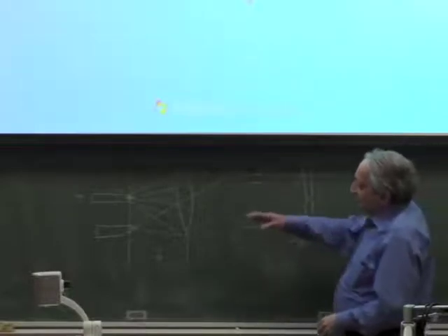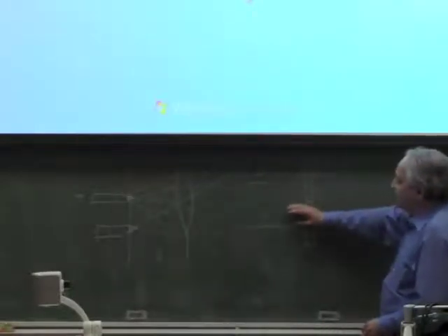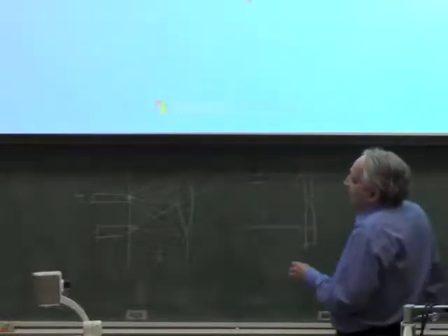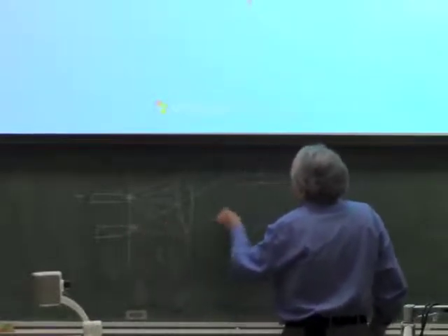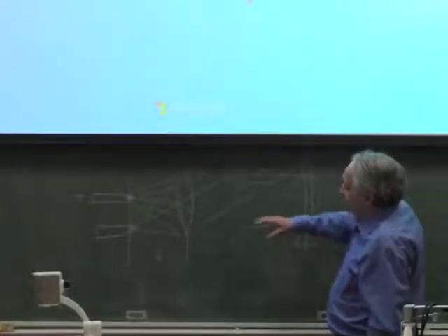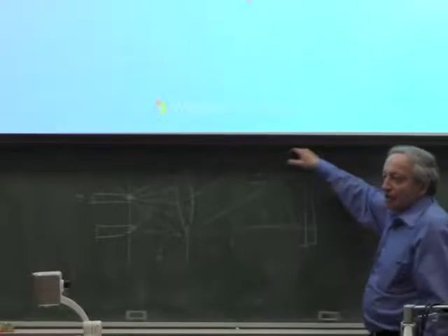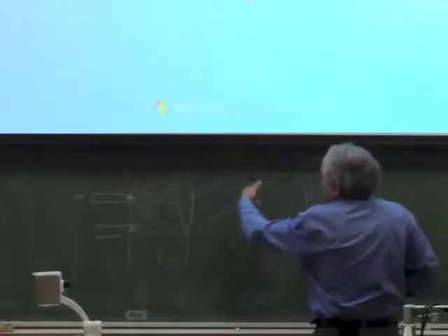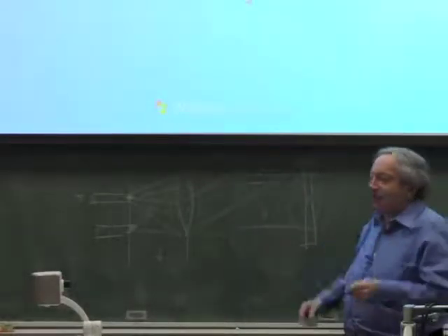Now it is true that if the LED is non-uniform, if I turn it, I'll get the light spot a bit brighter here, a bit brighter here. There'll be a small error in position. But if I move the LED to here, this whole beam will actually go this way, because the central ray going to the center of the lens is not changed. So if I move the LED, this whole beam will steer. And I showed it to you last week with the laser pointer and the lens.